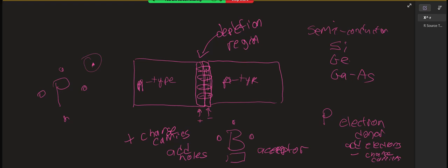I haven't talked about this yet, so I'll say that this is called a p-n junction. So if we're labeling this on the tiny little picture I gave you, that's a p-n junction diode. What's the name for the area in a p-n junction with nearly zero mobile charge carriers? Depletion region. They're not mobile because they're all tied up.